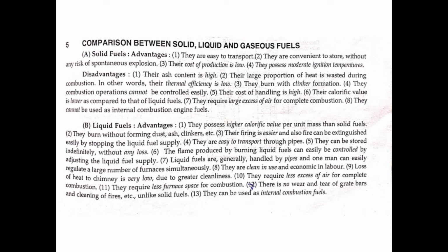They are clean in use and economic in labor. Loss of heat to chimney is very low due to great cleanliness. They require less excess of air for complete combustion. They require less furnace space for combustion. There is no wear and tear of grate bars, and they are used as internal combustion engine fuels. These are some advantages of liquid fuels.